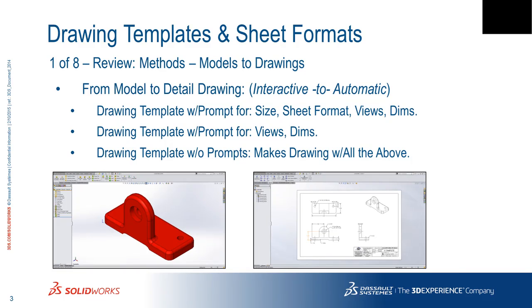So through the automation process, the stuff that's built into core SOLIDWORKS, you can go from a part to a drawing in as little as 4 clicks. And you can have your front, top, right, isometric view. You can have the model dimensions brought across, and you can fill out the title block.